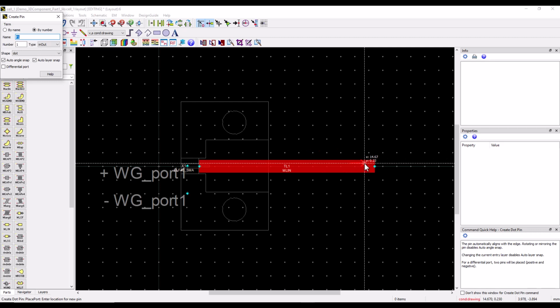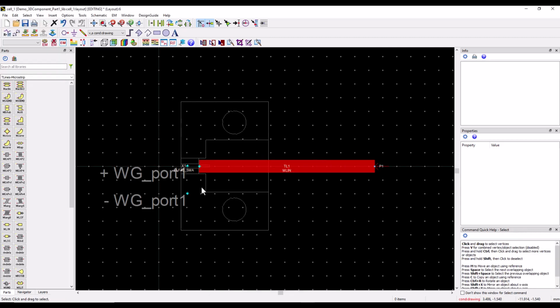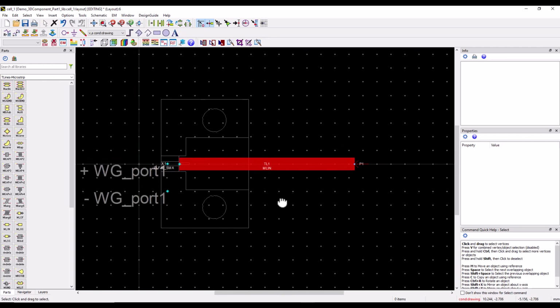Now, once you are done, very simply, let's place a pin on this end of the transmission line. Otherwise, you can drag and drop another connector and connect the SMA connector on that end of the line as well. But right now in my demonstration, I'm only going to show one connector. Alright, so now how will the connector body connect to the ground, which is on the M2 layer? Remember, we synthesized a line where we used the M2 layer as a reference or ground return. So here I will enable the grid again.